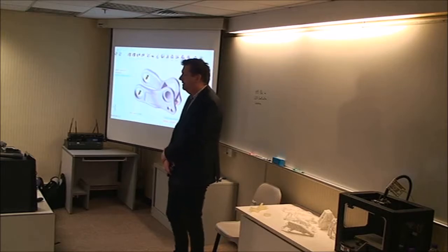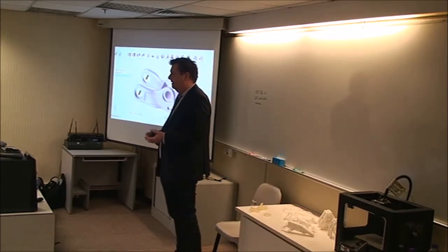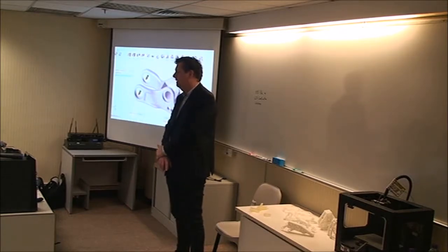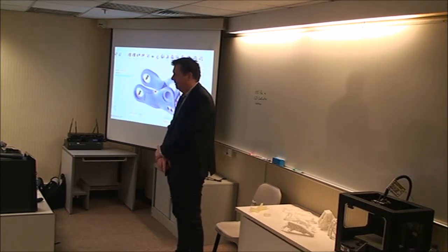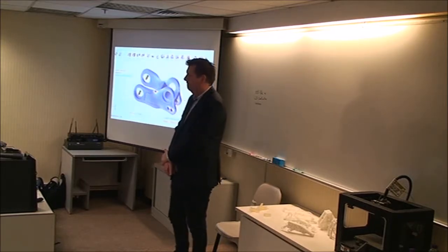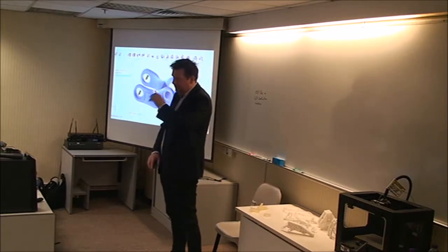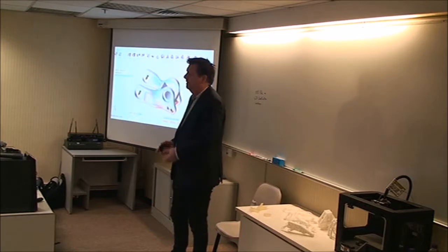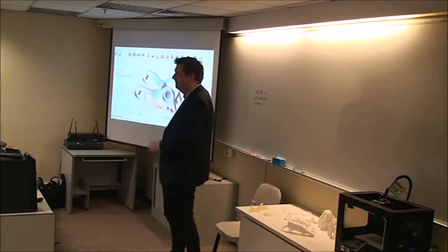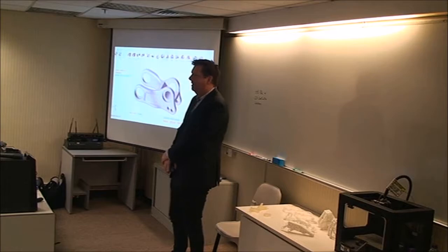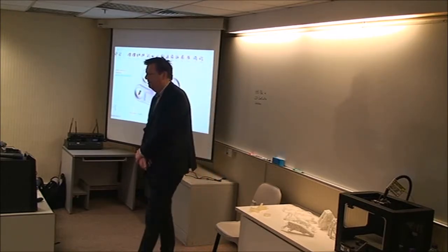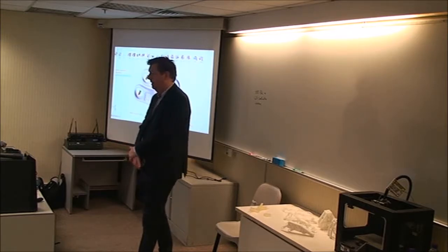Yes. So the very first thing to do is you put your loads and supports on your structure. So you see the little red bits have arrived. That's like a pivot. There's some forces in there as well. You hit the analysis button, and very quickly you can start looking at results. And if you've got CAD data, you can just drag and drop it into your Inspire window. There's only 3 or 4 little icons at the top you need to learn to use at the very beginning. You can put your loads on and really quickly just analyse your model and find out how it's performing.